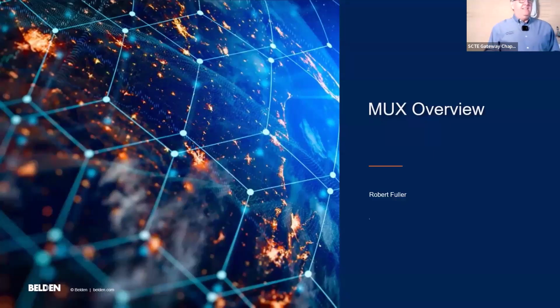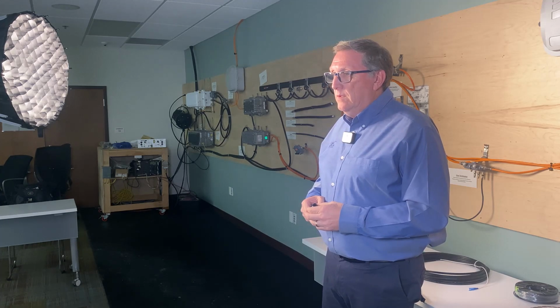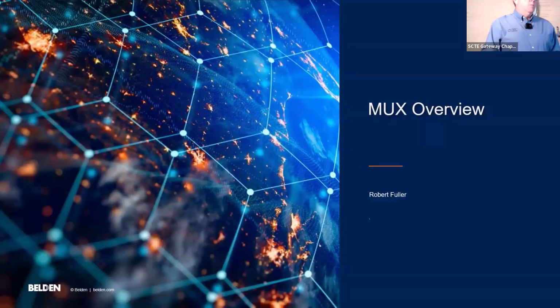Questions? Okay. So a question from the chat. Is there a difference in bulkheads and attenuators when it comes to inserting two different style fiber jumpers into them? That question was from Dennis Russell from Madison Communications. Dennis, are you SC to SC? Is that what you're talking about? Are you talking about from manufacturers? Because you can't match an LC with an SC, right? And so the attenuator should be fine.